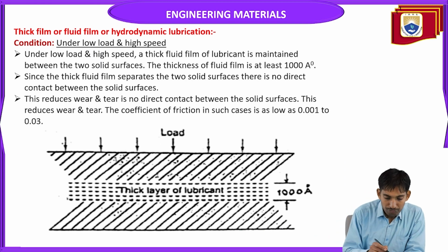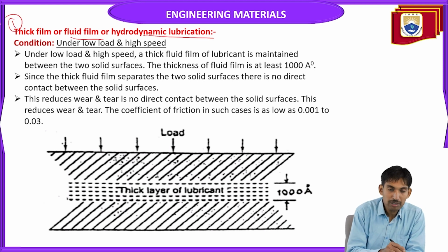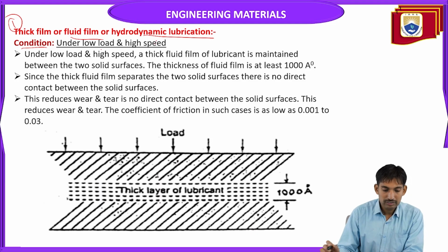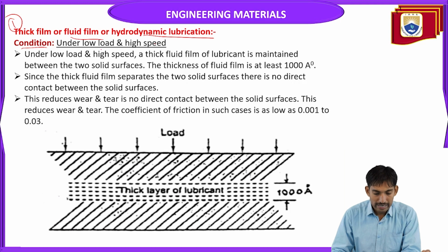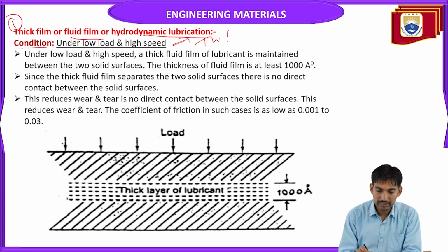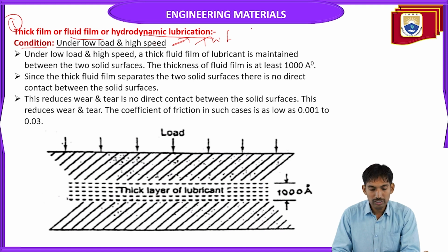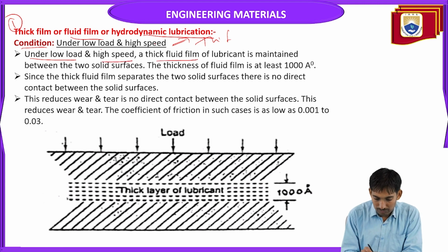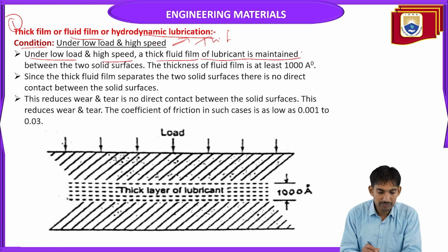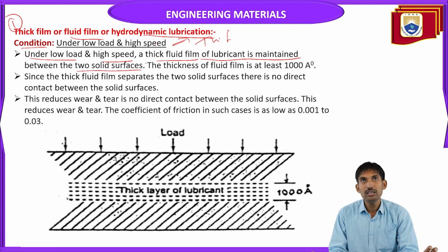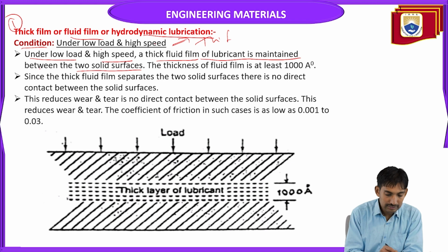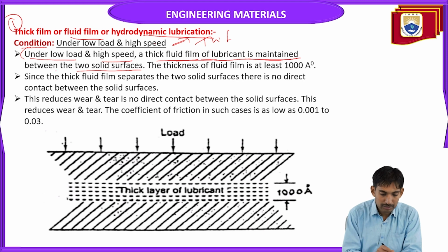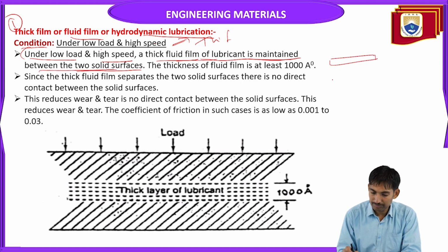Thick film, or fluid film, or hydrodynamic lubrication is the first type of lubrication mechanism. It works under low load and high speed. Under low load and high speed conditions, a thick fluid film of lubricant is maintained between the two solid surfaces.